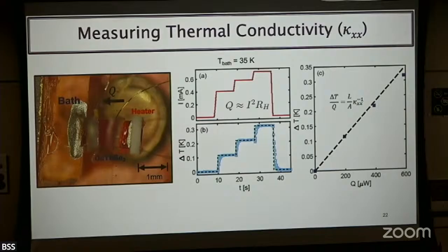And then here comes the steady state. We don't want to measure temperature around here, because the divergence of the heat current is non-zero in this region. So the delta T is the temperature difference between two different locations. One is closer to the heater, and we assume a one-dimensional temperature profile; the heat current is mostly one-dimensional. So the equitemperature lines will be perpendicular to the heat current.